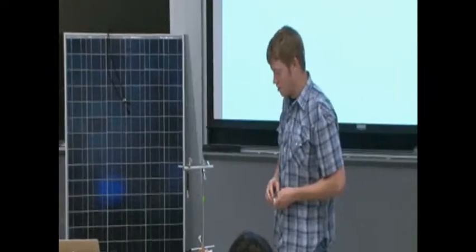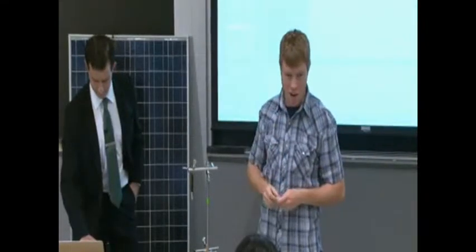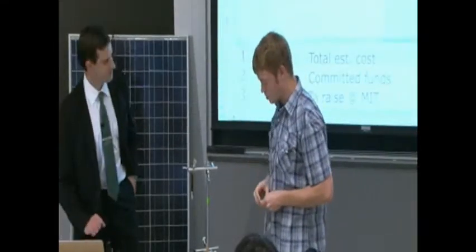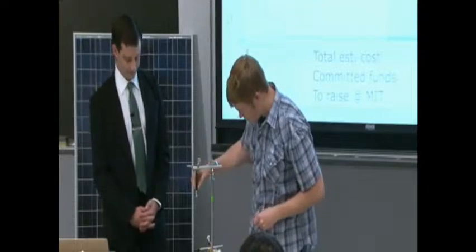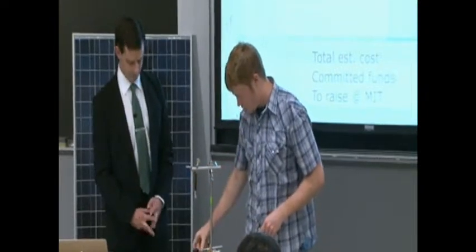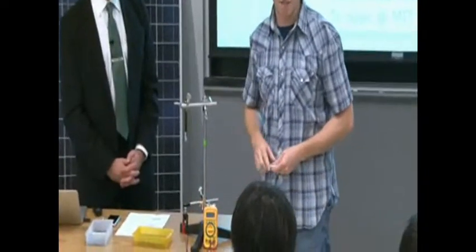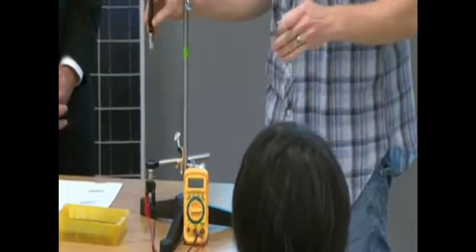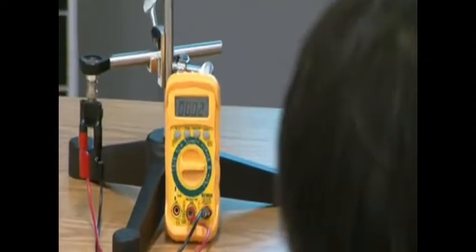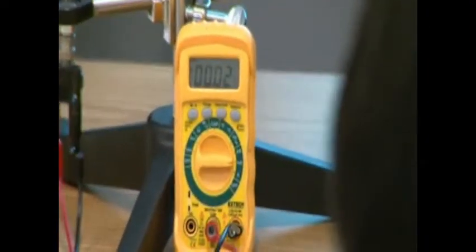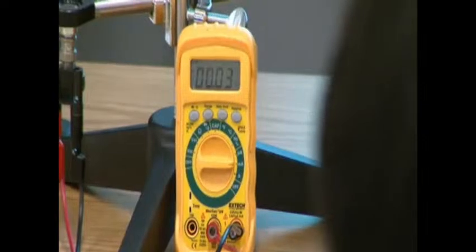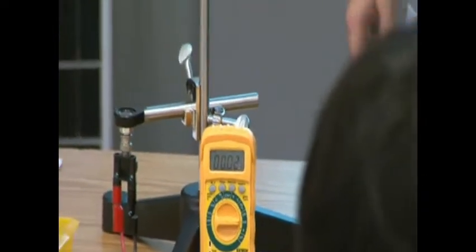So if you guys want to play along, that's fine too. I know there's lines on the side of your notes. You can make a little graph paper, and it comes out looking really nice. So basically what we have is a laser pointer and a photodiode. And the current out of this photodiode is directly proportional to the light hitting that photodiode. And it has a quantum efficiency, which we're going to learn what that is in a few lectures, of about 60%. So of the photons hitting it, you'll get a certain number of electrons out, and that ratio is 60%.